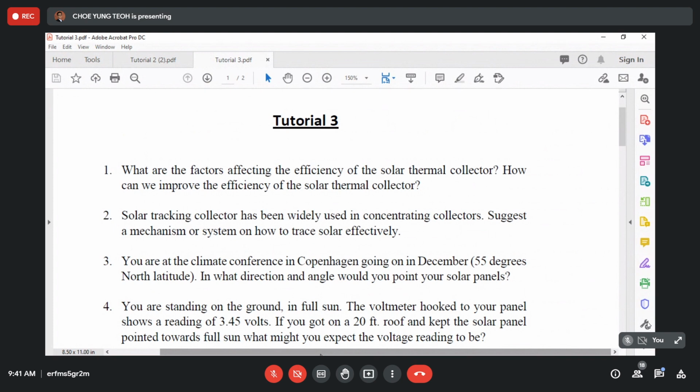Okay, what else? How about the fluid inside the collector? Will it affect anything? Okay, the fluid inside the collector must have a very high heat capacity. Yeah, okay, you want to use methanol. Okay, but what's a good thing about methanol? Methanol has a very low freezing point and a light density. The advantage is it won't freeze. You have a two-phase liquid, okay? But the disadvantage is you have a much lower heat capacity compared to water, okay?